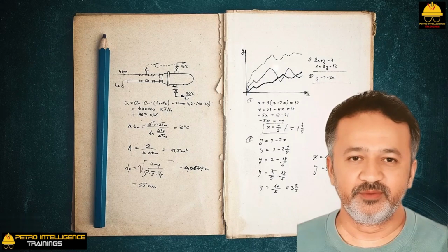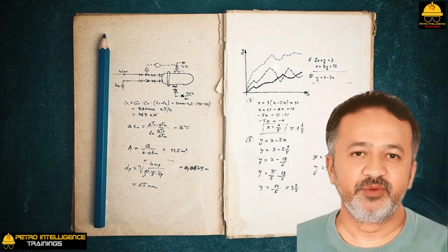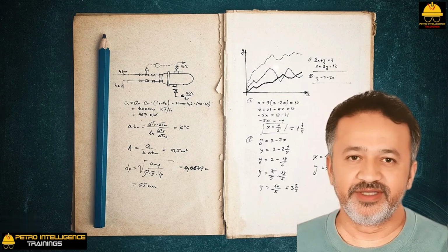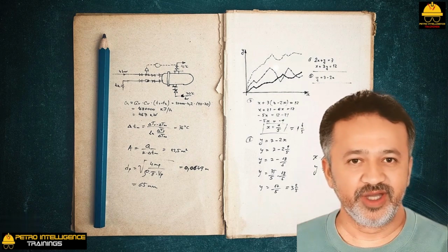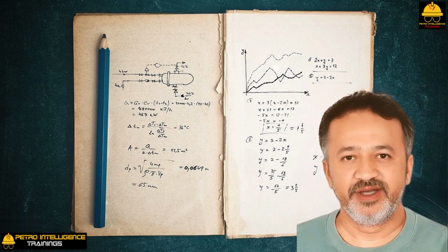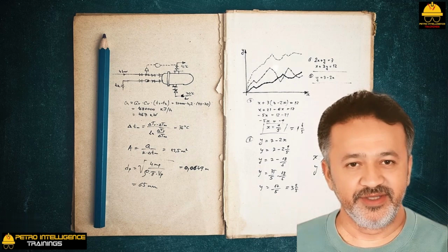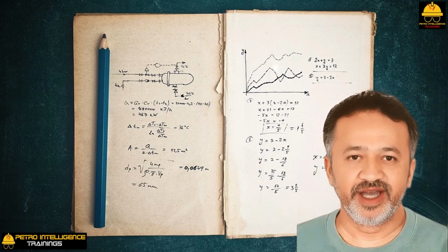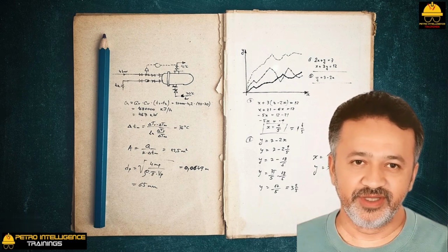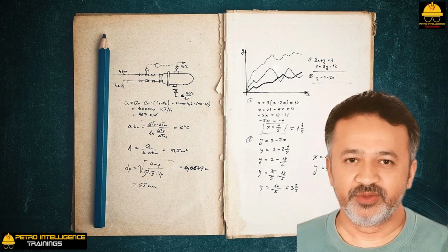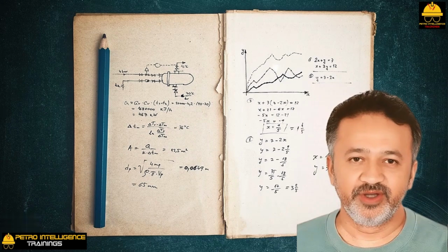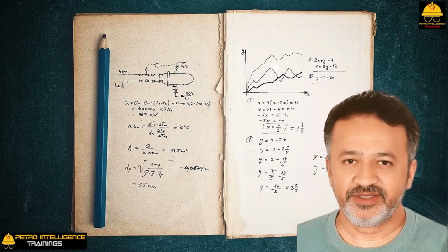Steam ejector temperature profile. The entire concept of thermodynamics, the conversion of steam heat into steam velocity, can best be observed on a vacuum jet. Let's say I have 150 psig or 10 bar saturated steam at 360 degrees Fahrenheit flowing to the jet. As soon as the steam enters the ejector through the steam nozzle, the steam cools off to about 90 degrees Fahrenheit. Don't take my word for it. Take your temperature gun and see for yourself. What happened to the missing 270 degrees Fahrenheit of the steam, 360 degrees Fahrenheit minus 90 degrees Fahrenheit? It was converted to velocity.